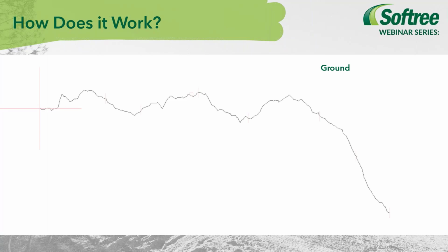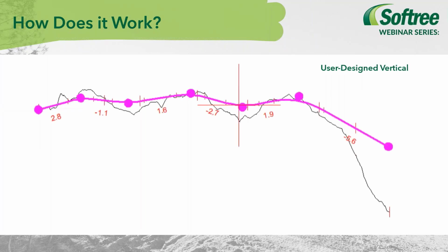So today we're going to focus on our vertical optimizer. For that, we'll need some kind of topo surface for our ground survey. Everyone here has probably done a traditional design, where you'll go through and figure out the alignment that you want to go with. Our optimizer takes that traditional approach and turns it into a semi-automated one. So it's going to leverage mixed integer linear programming in order to generate a vertical alignment for us.